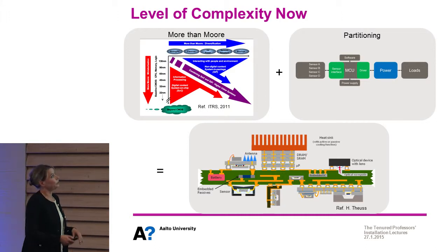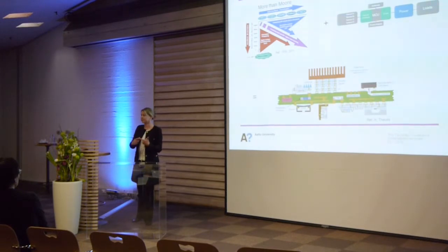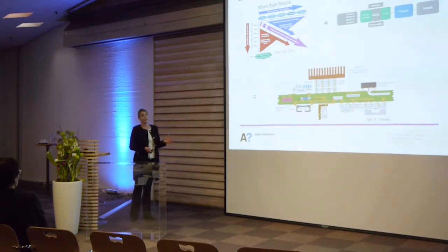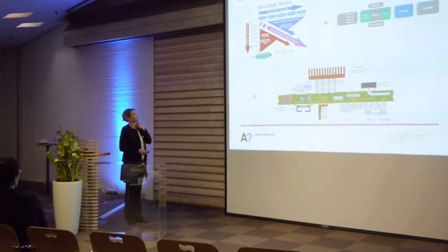So typically what you will have is what we call heterogeneous integration. All those technologies for power, for sensors, for other analog functions, for digital, they are very different, and the cost of manufacturing is so different that we want to keep them separate, even though it would be technically possible to integrate more on a single piece of semiconductor.